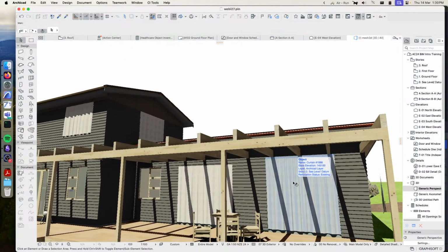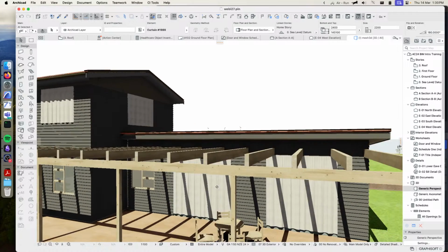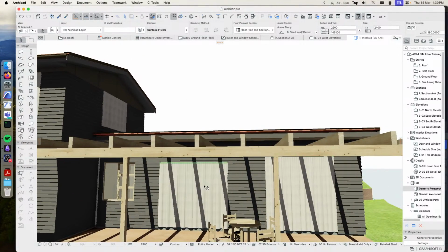So this would be useful for doing shutters, for instance, applying lintels, applying curtains if you were to set it to use the inside rather than the outside of the reference line, all that sort of thing. It will just automatically place those objects onto the windows and doors that were selected and set them to the right size and location. So it's just shortcutting that job for you.